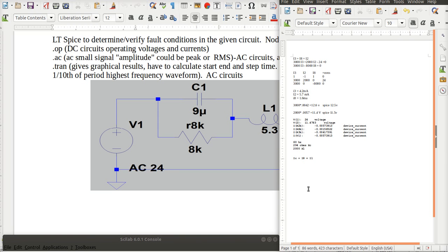Now 294 is a capacitive reactance, and in the complex plane that is a negative Y direction, if you will. Resistance is always in the X direction, horizontal. Reactive components go up and down. So it's not like I did up here, it's not 3000 I3. It's going to wind up being minus 294 j, the imaginary operator, times IC. That's my first term.